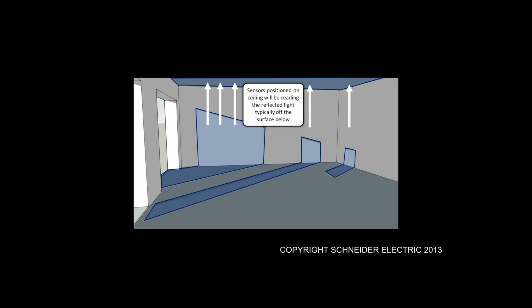In this particular case, where you've got certain beams of light coming through windows, doors, openings and the like, you might find that the sensor doesn't operate during certain parts of the day. So it could just be a case of throwing a mat down or something like that to reduce the amount of glare coming from, for example, a polished floor.